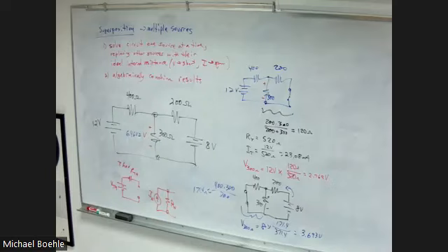So whichever one I figure out, I can go back and solve for the other one, right? If it's easier to find a short circuit current, find a short circuit current. If it's easier to find an open circuit voltage, find an open circuit voltage. If both of those are easy, I can use those two to calculate what the resistance is. What's true about the Thevenin resistance and the Norton resistance? They're the same, right? Remember, in source conversion the resistance doesn't change, the value just changes where it is.